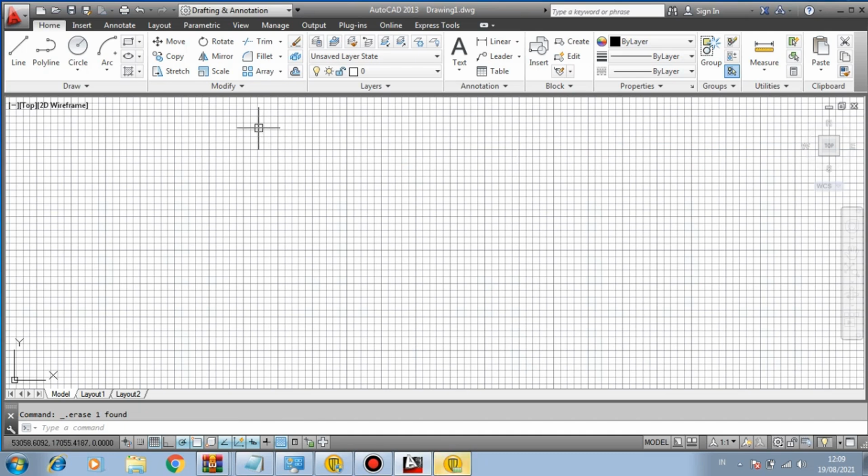Let's continue with the rotate function. Rotate is primarily used to turn an object. Click the object you want to rotate. Click the object, then click rotate. Determine the rotation axis point. It can be at the left end, top, or bottom. It depends on your needs. For example, here I click on a certain part. Now it asks you to enter the angle. What angle do you want? If not, you can just click directly to set the angle. This is rotate. Click the object, then click rotate. Click the object again, then turn it. Just like that. Rotate.